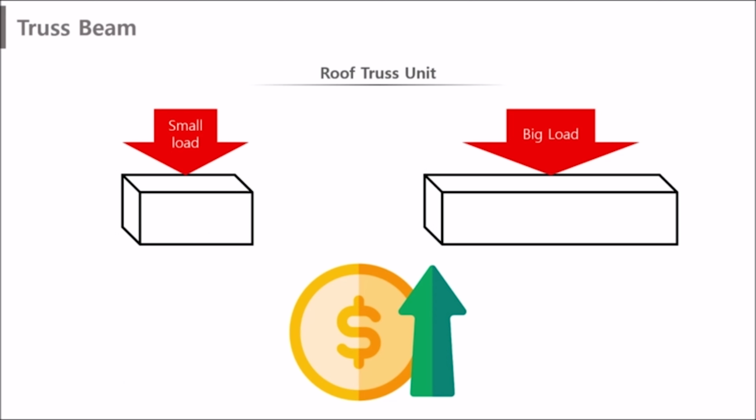The size of truss members varies from 200 mm by 200 mm to 700 mm by 400 mm, creating an economical effect by placing large cross-section resistant members on the heavily loaded side and a relatively thin section on the relatively low load side.